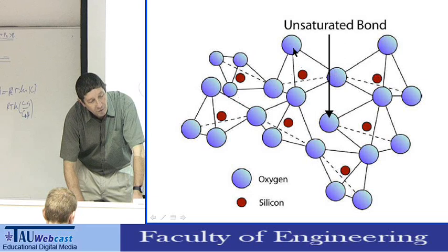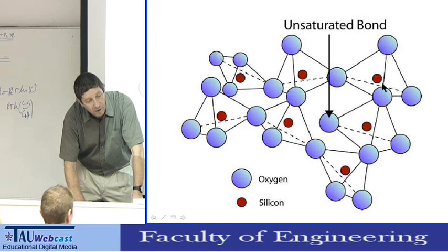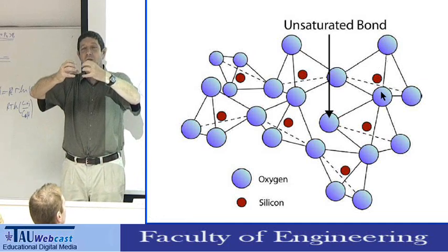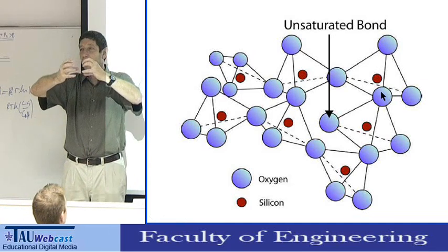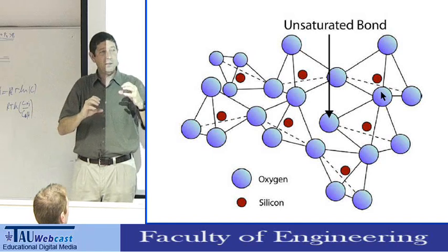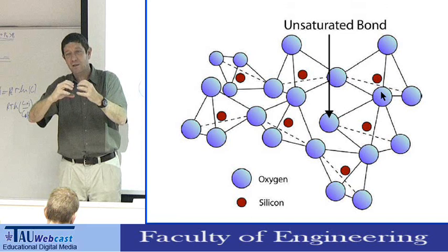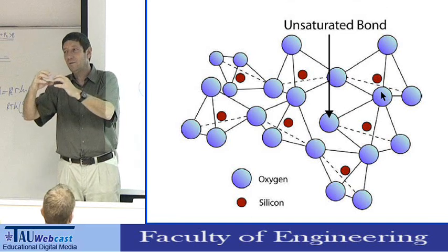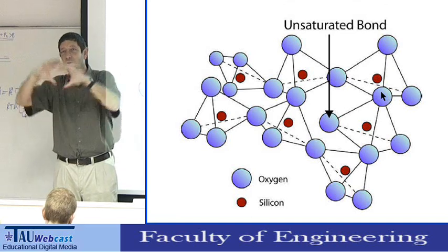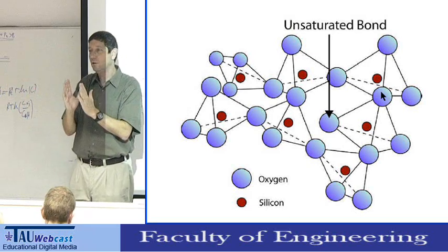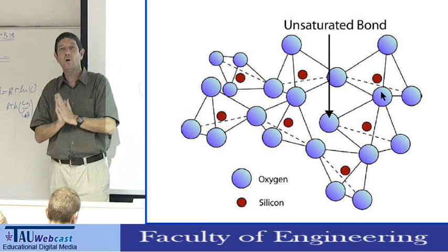So this is a tetrahedral, and it's connected by this silicon atom. Now, every tetrahedral connects through one atom, so they can rotate freely, basically. So if you have one tetrahedral next to the next tetrahedral, it can rotate slightly. The next one can be in a different position. So the whole structure has a short-range order, but there is no long-range order.